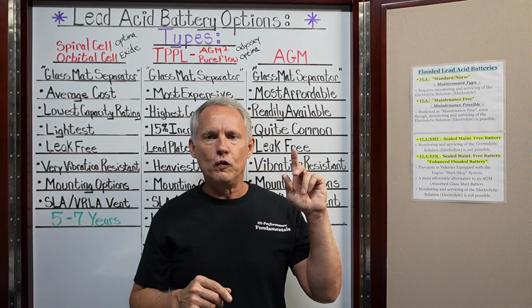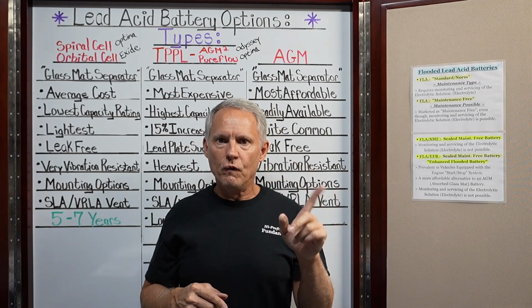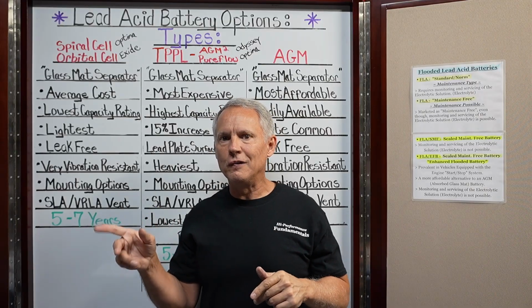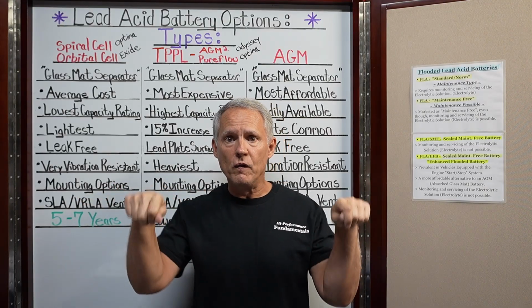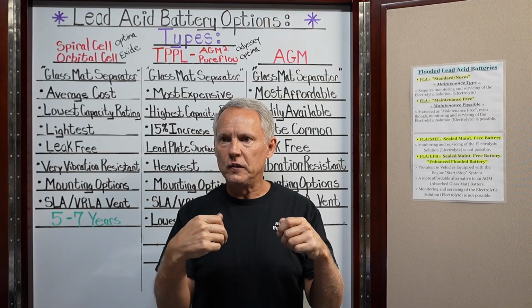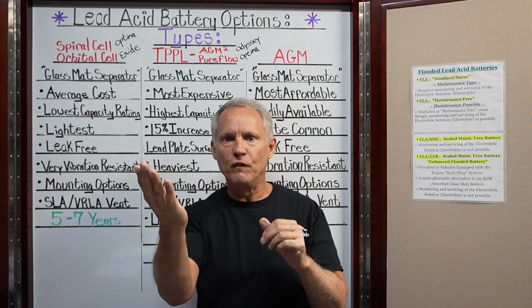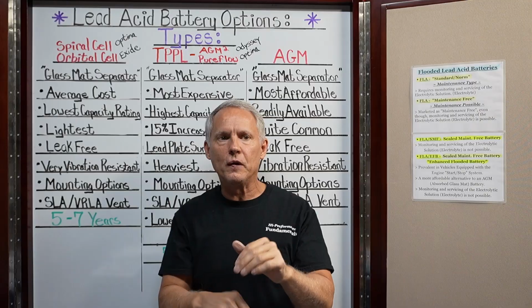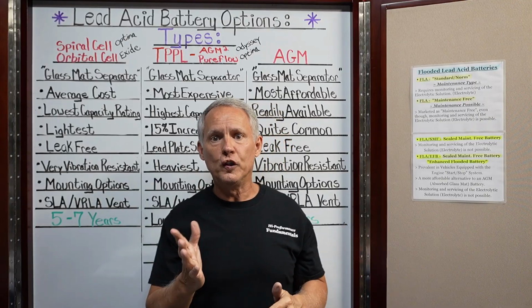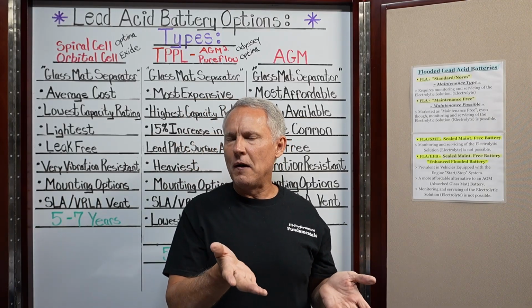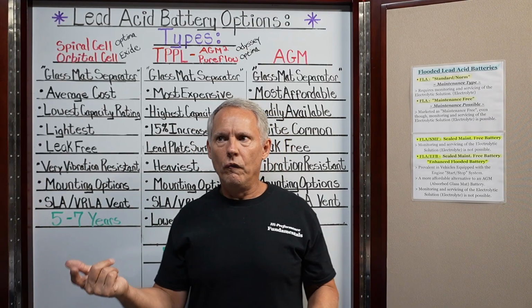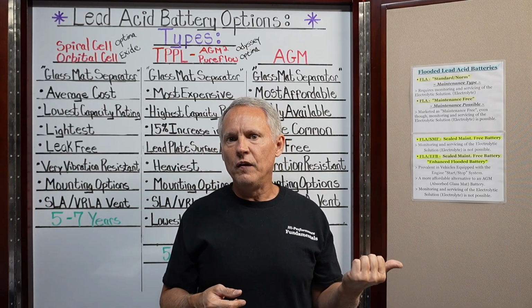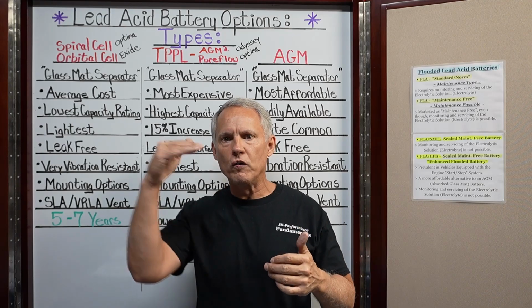When the alternator is charging that 12 volt battery, it's charging it somewhere around 14 to 14 and a half volts. If you were to check the battery voltage while the car was running, you're going to see somewhere between 13 and a half and 14 and a half, but while it's charging the battery, 14 to 14 and a half is what you're going to see. Now think about that. That's what the alternator is designed to do. Well, that's not even the voltage of a 14 volt battery fully charged, let alone the charging voltage, which has to be greater.